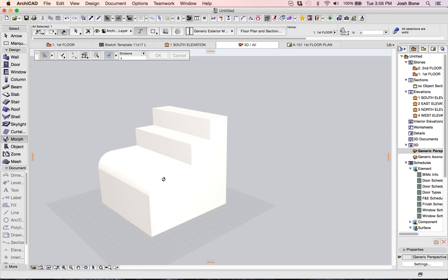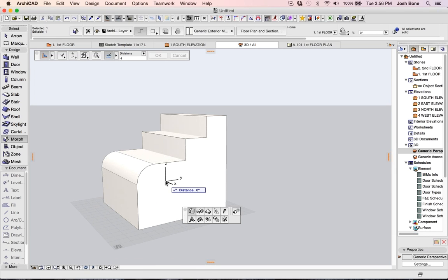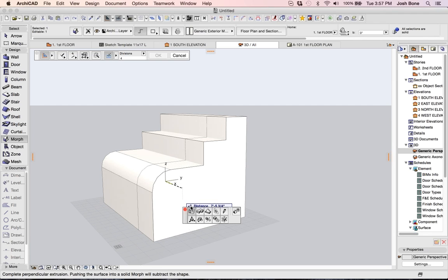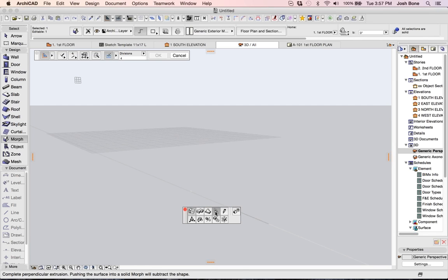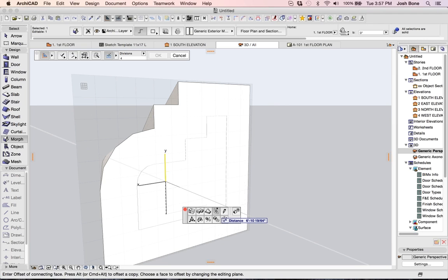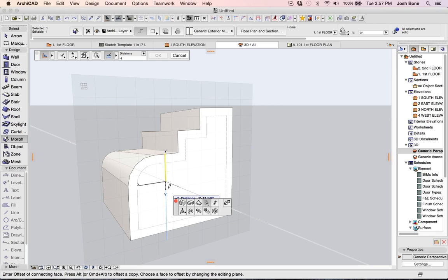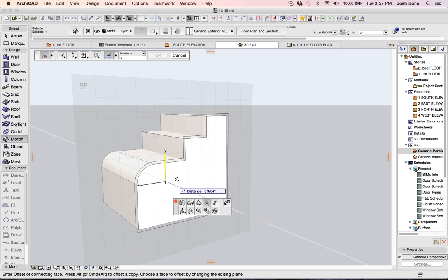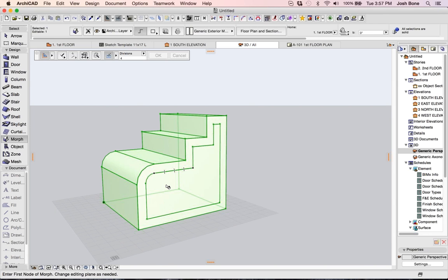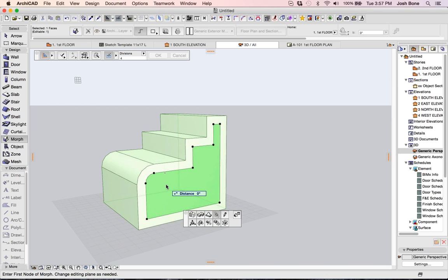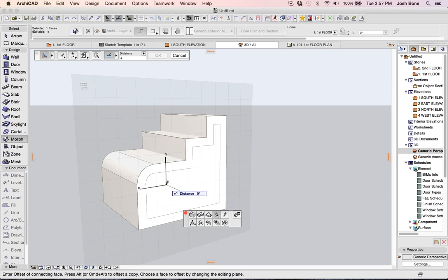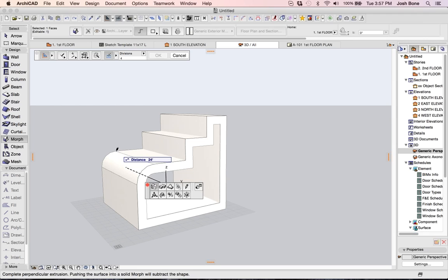You'll see if I rest out here on the front, I click here now, and I want to manipulate this. I have the ability to come back in here to my offset tool, and with my offset tool, I can shrink this down. This plane, I can go out larger. If I hit with an option here, let's say I want to do a copy of this, if I hit the Alt key, the Option key on my Mac, the Alt key on my Windows, I can come back in here now and set this to 2 feet. And I can set that, and if I do a Shift Control on this plane, and now come back in here and click, I can push this all the way through, and I've cut an opening in that now.